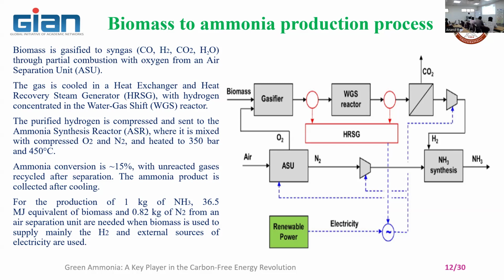So here, unless you understand this one, it is very difficult to know how, by using our gasifier, this is going to be used. In the gasifier, we are supplying 20 to 30% of air. In air, 1 kg means, in terms of mass basis, 0.23 is oxygen, the remaining 77% is nitrogen. So we are interested only in oxygen, not nitrogen. So if you put 20 to 30% air, corresponding to that stoichiometry, we will get the relevant oxygen, and it's going to react in the gasifier.